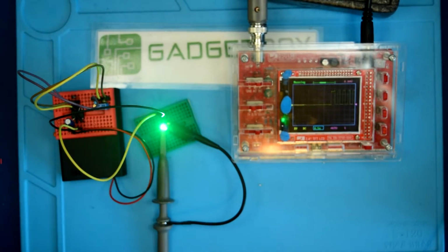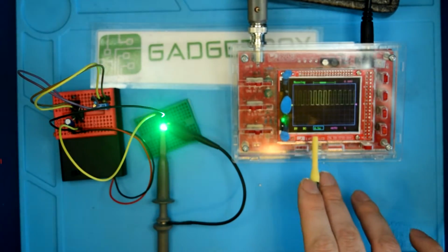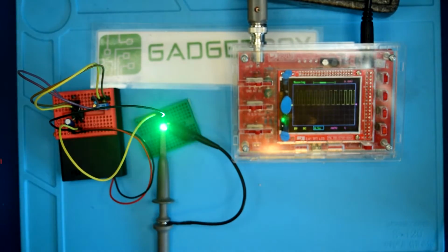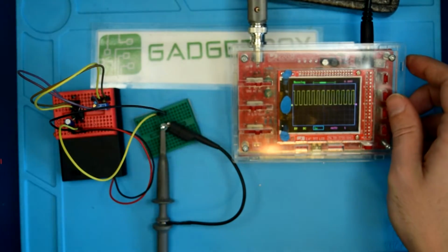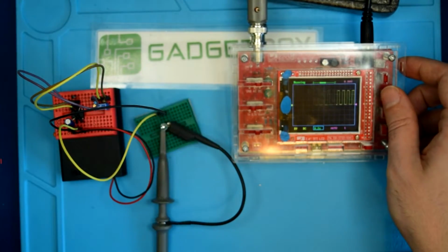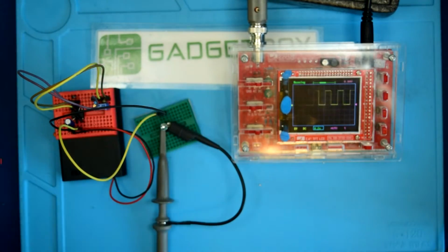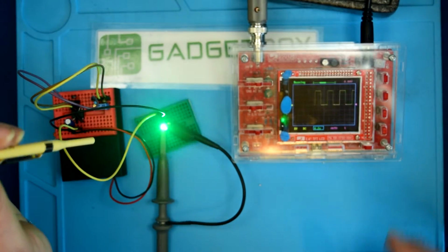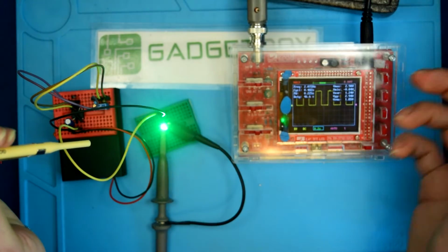There we go. So here are pulses on the oscilloscope. Sorry for the strobing. I actually see that too, so that's just the refresh rate of the display is kind of slow. Let's actually decrease our time base here. No, that's the wrong way. I want to go this way, I think. Is that the right way? Yeah. So right now we're at 50% pulse width modulation. We can actually look at the duty cycle here is, well, 46.6.